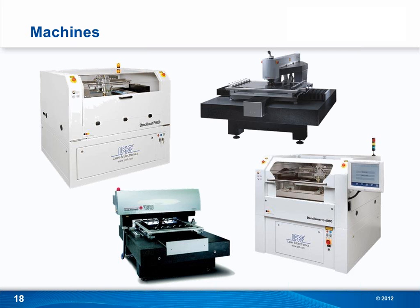So when you look at the image, the top right laser is one of the older versions, and that upper table that holds the metal sheet rides on top of the Y movement system. So that means the whole X movement system has to be transported for a Y movement. So there's a lot of mass. In the bottom left image, that particular system, you still have the Y movement, but actually the laser beam is moved in the X direction, so there is much less mass to transport.